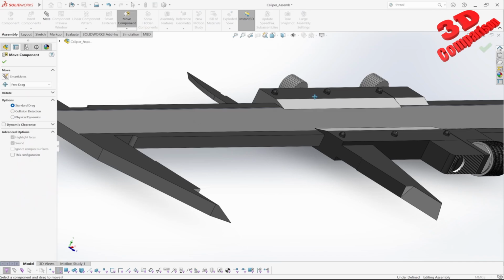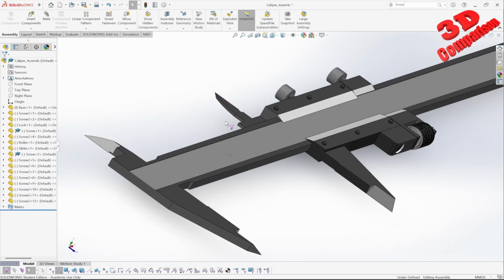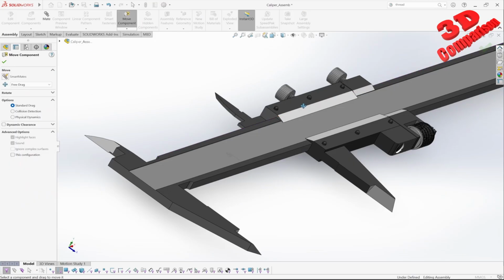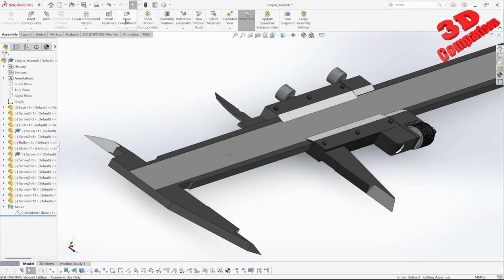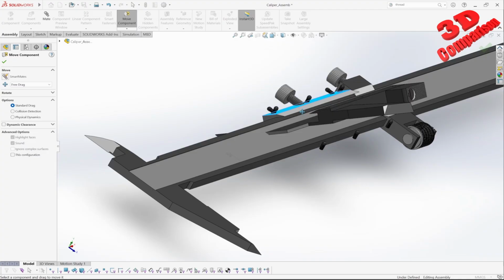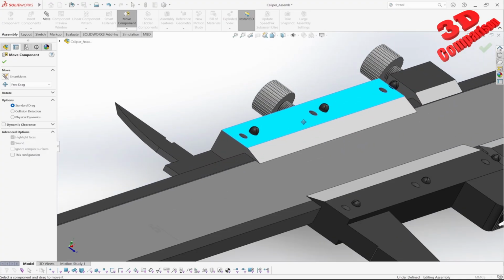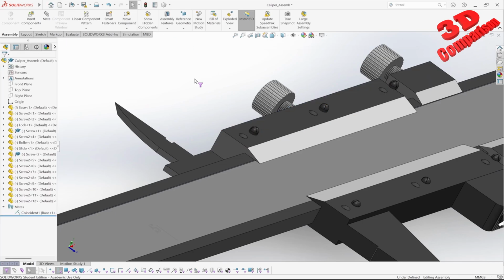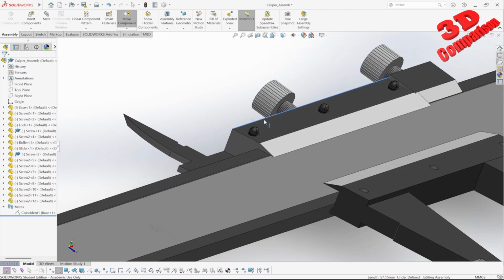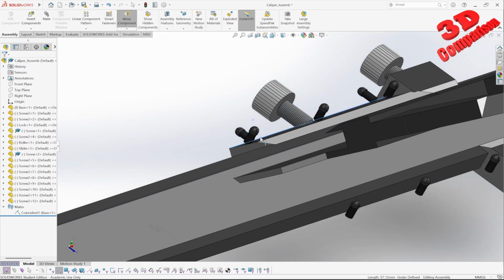But now, if I move this component, we currently have the base locked and we have that coincidence. But if I go and move, you're going to see that I cannot actually move this component. This is because I still have my selection filter on, the edge over here. If I just disable that, we're going to see that now the move tool will work like this. That part actually moves because it isn't constrained, but initially I wasn't capable of selecting that component since I had E, which is that edge selection. If I select an edge and start moving, this will actually allow me to move. So keep that in mind because this is a little bit tricky.